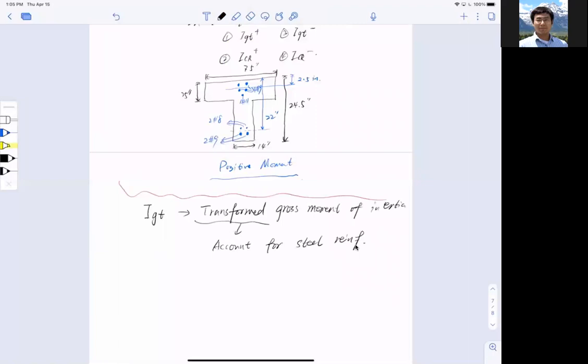Okay, so whenever you see this little subscript T here, it means that if I have reinforcement in this I-regular section, whether at the top or at the bottom, when I transform, I will have to remove that first and add little wings here. And these little wings here are (n minus 1) As, and this top is (n minus 1) As prime.